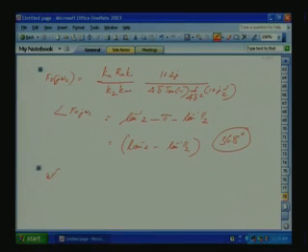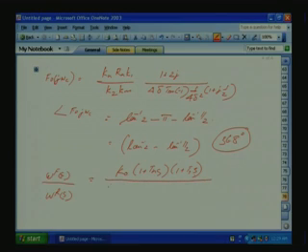Our previous transfer function omega F(s) divided by omega R(s) is equal to K0 into (1 plus Tn s) into (1 plus T1 s), divided by Tn delta s cube plus Tn s square plus K0 K1 Tn s plus K0 K1.